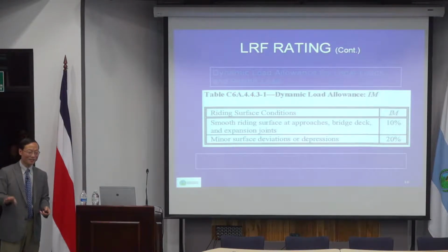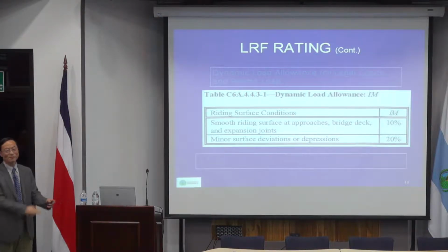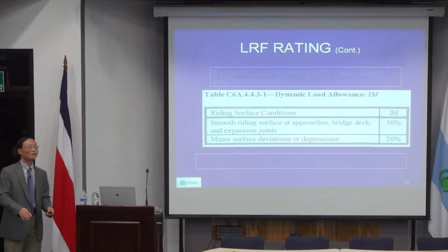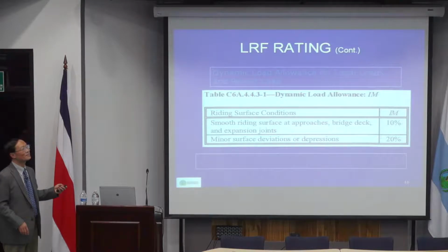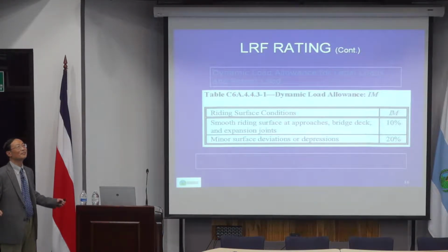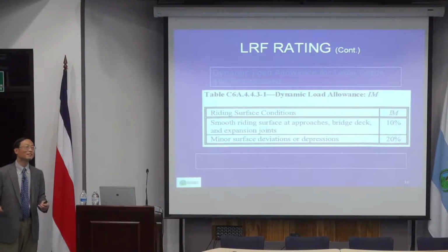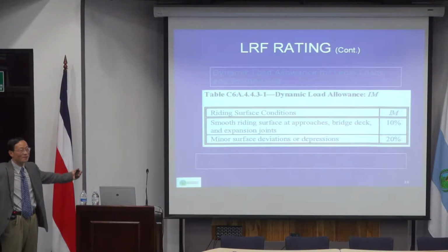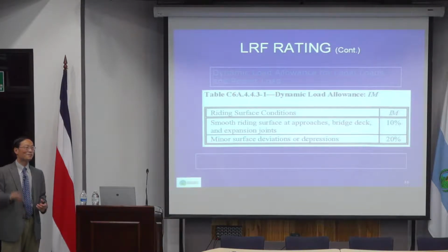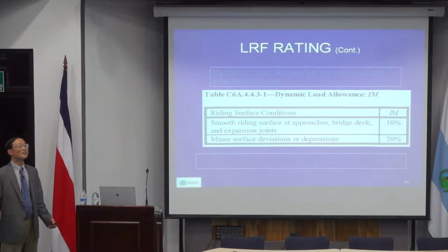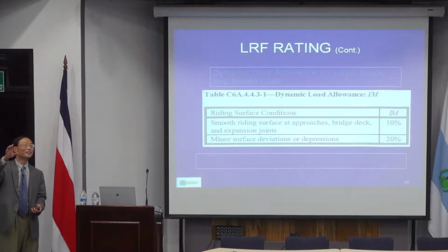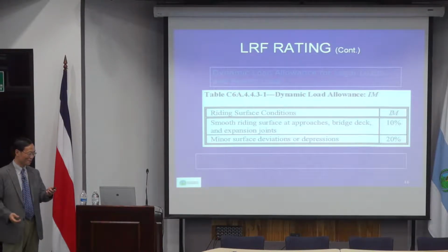And also impact: we said the impact is a factor of different conditions. If we have a very smooth bridge, the impact will be very small, and if we have a very rough surface, the impact will be larger. That only addresses smoothness, but in reality, the impact is also a function of frequencies, as I said. So you can actually slow down the truck to make the impact much lower. Or you can do a load test. If you have a very long span bridge, like a suspension bridge, their frequency is very low and your truck frequency is very high, so they don't match at all. You can do a load test to see what the impact is, and probably it will be almost 0, or 2% or 3% instead of the 15-20% range, so that effectively you can increase your load capacity to pass over these bridges.